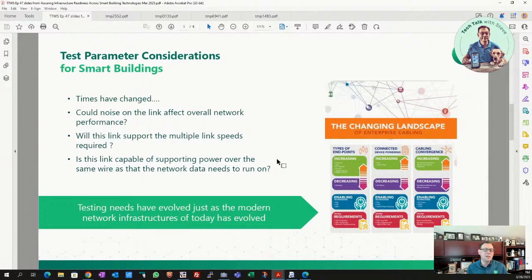That comes into that TCL and ELTCTL testing I talked about. Those parameters are an optional pass-fail limit in a certification test, and we run them in the same 6-second Cat6a auto test on our certification tester. So it doesn't add any time to that test, but it gives you an idea of how well the cable is constructed regarding being resistant to noise interference.